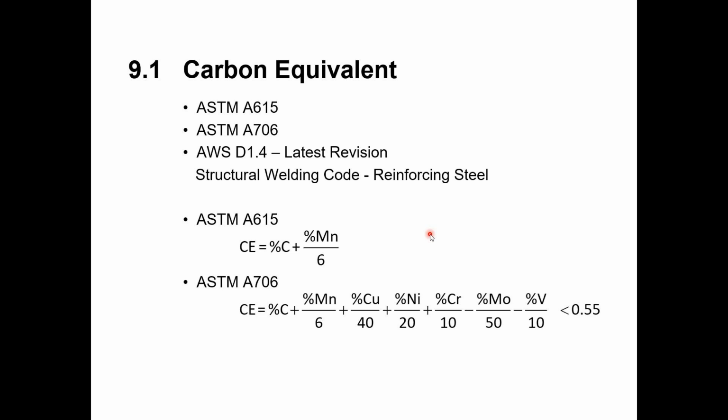And you go into this table, and it says carbon equivalent range percent, and that's on the left-hand side. Then the second column of information is the size of the reinforcing bar. And third, this is for shielded metal arc welding with low hydrogen electrodes, gas metal arc welding, or flux core arc welding. So this is specifically talking about weld types that are not like a stud gun, where you're shooting the studs on, which we'll talk about a little bit later. These are the typical types of welding you would see for doing something like this.